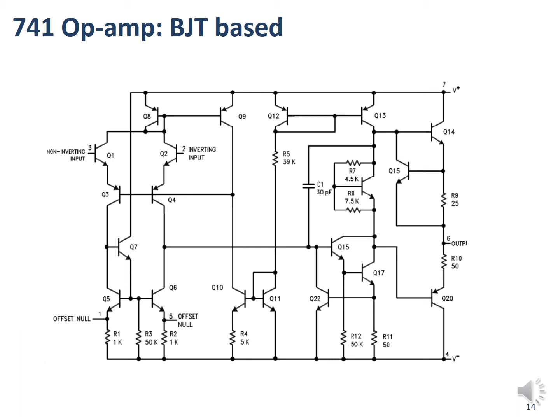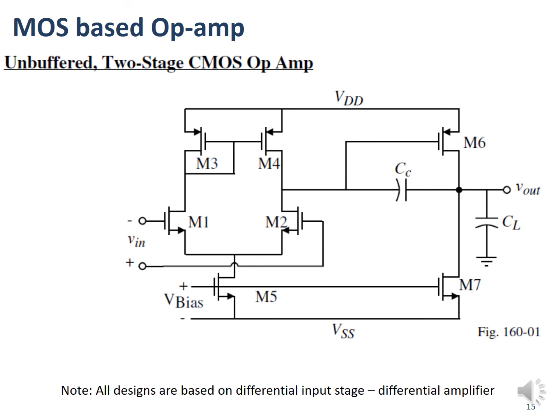So those inputs that I see as the inputs to the op-amp go into the base of these 2 transistors, and that turns those transistors on. Then we need to understand what happens when that occurs and how we make that work. But really what we're doing is we're seeing the difference between those 2 signals, and that's the basic function of the op-amp, of course. And of course I can build op-amps with other types of transistors as well.